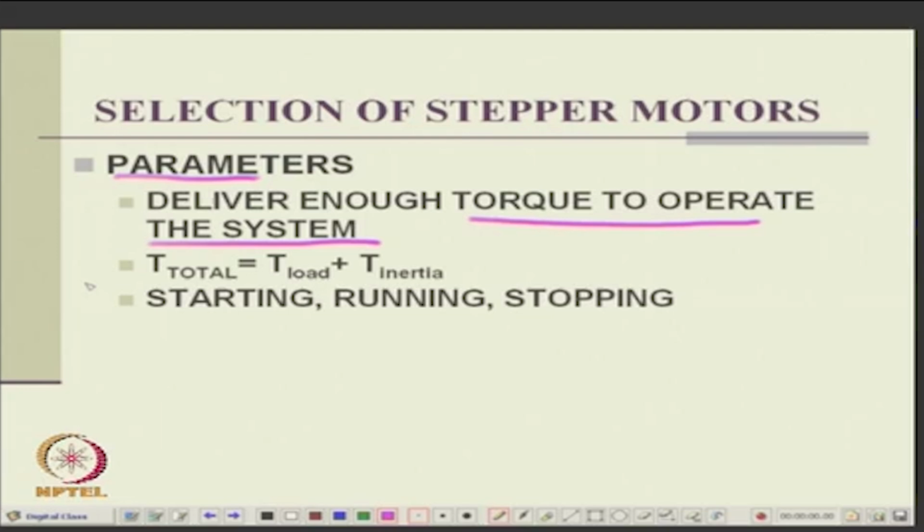Now, how do you decide what torque is needed to operate the system? The total torque will be load torque and inertia torque. There is a fixed load torque, and there is an inertia torque. The torque must be sufficient to start the motor, to run the motor and to stop the motor. It is not just that it can run.